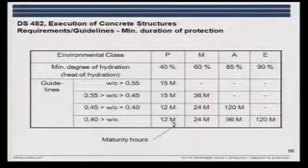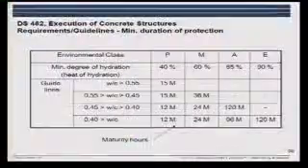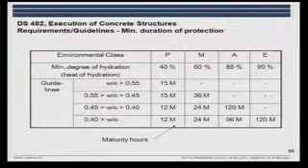If you take this, 12 hours at 20 degrees. If it's in Europe, it would be 20. In the US, sometimes you will see that they use 23 degrees, but it's a reference temperature. And that takes into account that if the structure is exposed to low temperatures, you need longer time to have the degree of reaction you actually need.